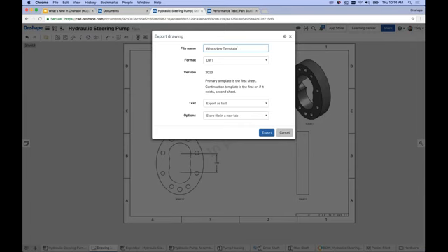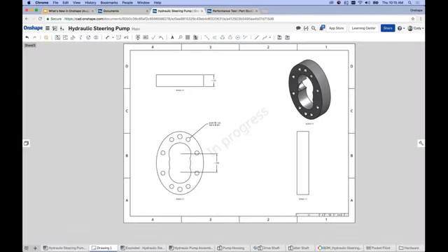So that's how to take all the customization you've done in the drawing properties flyout and make it a template that you can use over and over again. That's probably one of the most common questions I get when I show that drawing properties flyout. But keep that in mind, especially the store file in a new tab. That will actually save it to a new tab within the document, which means it's automatically usable the next time you go to create a drawing. All right, so a few questions.